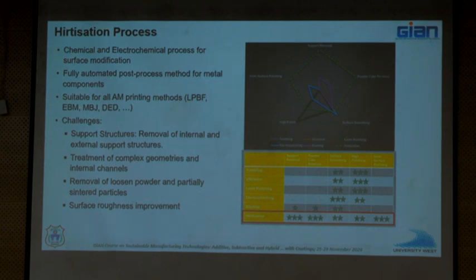I don't know why they advertise it like this, because it's obvious it is material specific, not process specific, but all these marketing guys write all sorts of stuff. But yeah, if you have, for example, Inconel 718, there will be a certain protocol. If you have stainless steel, it will be something else. If it is a nickel based superalloy, which is slightly different, like Haynes 282 instead of Inconel, it will still be different, right?